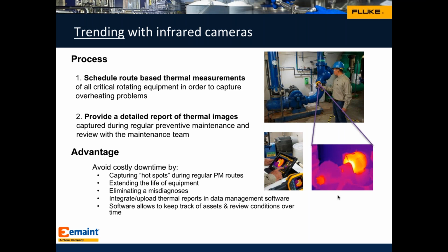And I think the most important thing that I like to do is to provide the data with a report. So do a quick report. It's great to capture 50 pictures, but if you don't look at them, if you don't trend them, it has no point. You want to be able to look at it from either the previous PM or on a weekly basis. If you take the picture at the exact same location, the exact same spot, you look at the motor, and if you start seeing the temperature increase or decrease in certain applications, then at that point, that's an indication. Obviously, with a thermal camera, you're talking about data you can look at over a period of days or weeks. So that gives you a little more leeway. But nonetheless, trending the data is really critical in the way you're looking at it.